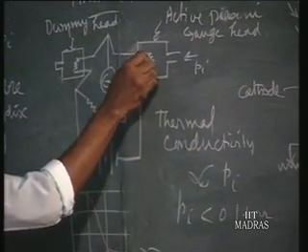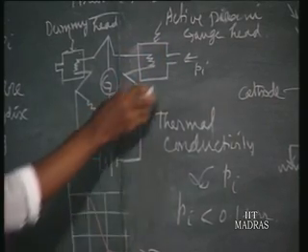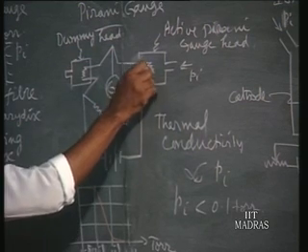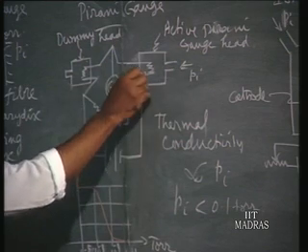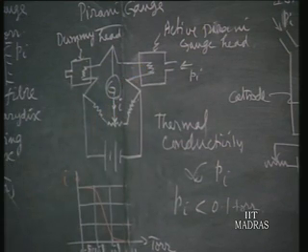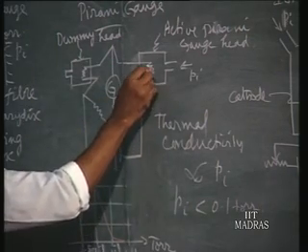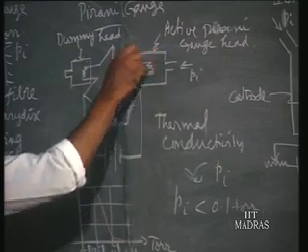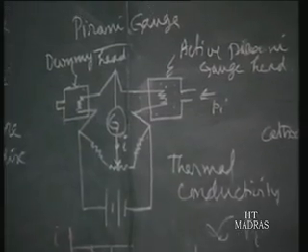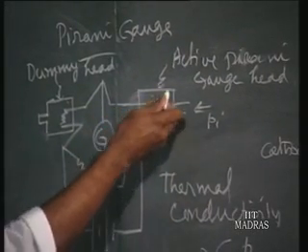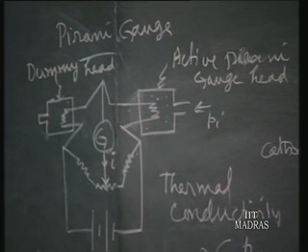For that you have the resistance element in the middle of this casing. It may be a metallic cylinder or a glass cylinder. The filament, made of tungsten or some good conductive material, is put at the middle of the cylinder. When you give supply to the circuit or the bridge circuit, it is heated up. This heat is taken to the casing by the molecules present. A higher number of molecules will carry proportionately larger heat, so the temperature will come down, and at that temperature it assumes a resistance.